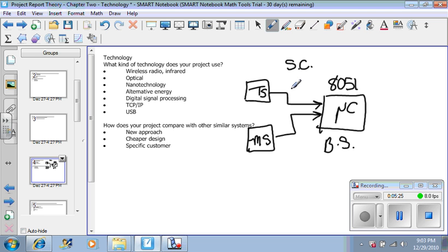In my project, I used a serial analog to digital converter because I wanted to reduce the number of wires and reduce the size of the chip. I selected a motion sensor called a PIR, which really detects heat. It uses the body's heat to detect motion.